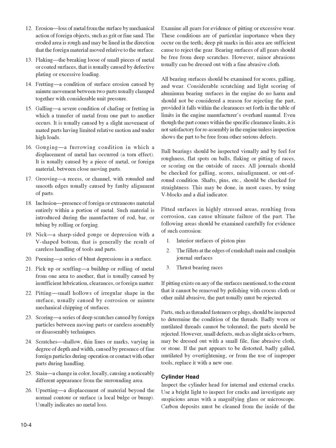21. Pickup or scuffing, a buildup or rolling of metal from one area to another, that is usually caused by insufficient lubrication, clearances, or foreign matter. 22. Pitting, small hollows of irregular shape in the surface, usually caused by corrosion or minute mechanical chipping of surfaces. 23. Scoring, a series of deep scratches caused by foreign particles between moving parts or careless assembly or disassembly techniques.